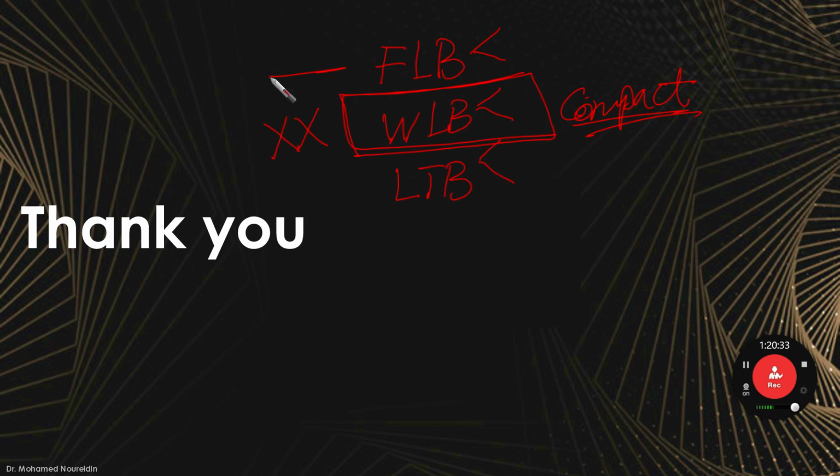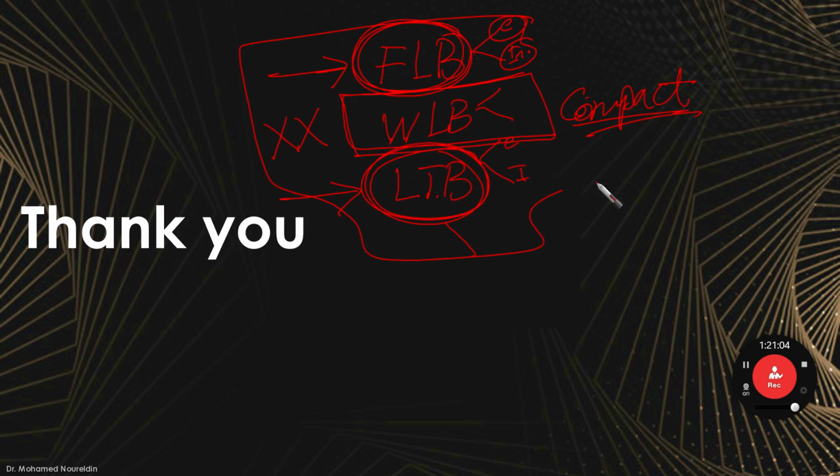Then we always need to check the flange local buckling or lateral torsional buckling. This is what we need to check every time. By checking, we found that sometimes a local failure mode would happen if FLB would occur, or a global one, which means the whole section, if it is lateral torsional buckling, whether elastic or inelastic. This is the summary of what I have explained today.